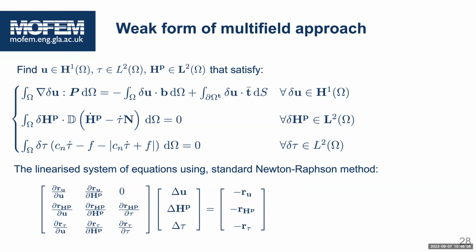Can we say this is something like a higher order or some n-th order DG method? No, because we are still using the classical formulation for the conservation of linear momentum. I mean for this field, for tau, for example. No, because when you use DG, you have a special integration over the skeleton, which bonds the fluxes, the transfer of the fluxes of momentum across the elements. Here we don't have to do that because we don't have an equation which requires it.